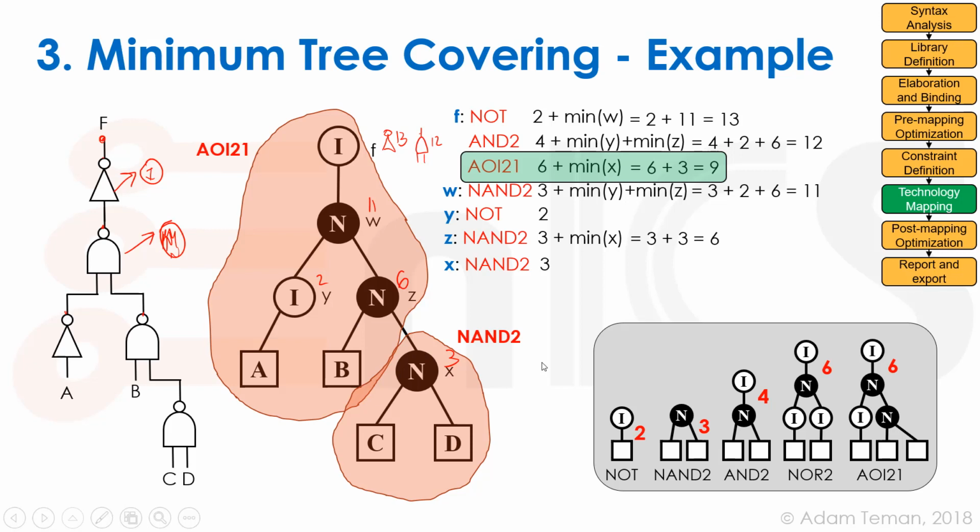So that is how we do our technology mapping, and that allows us to move from our generic standard cell library into a technology-dependent standard cell library, using our specific standard cells that are right for us.